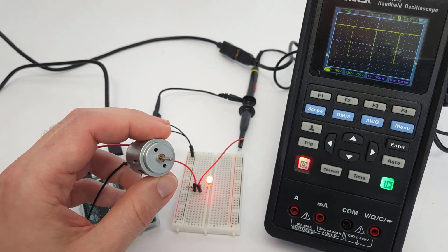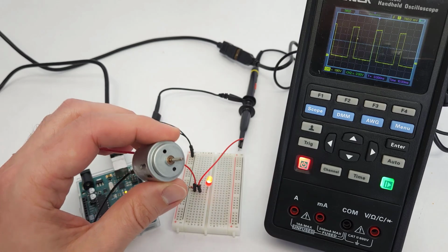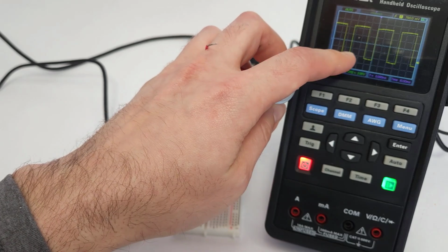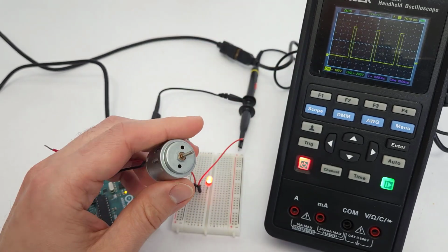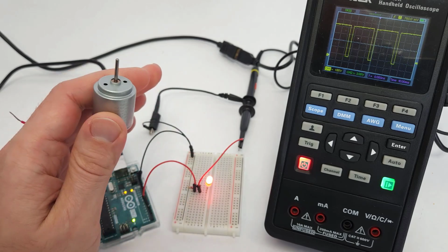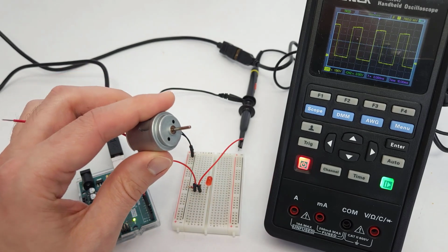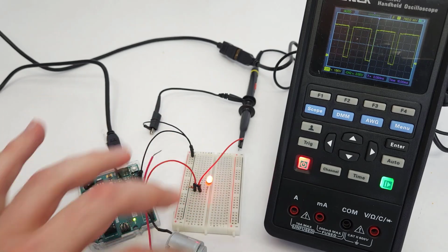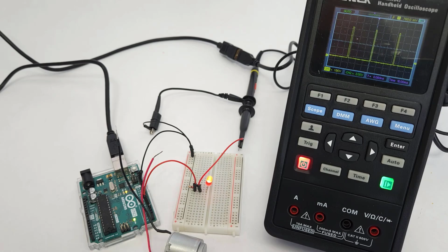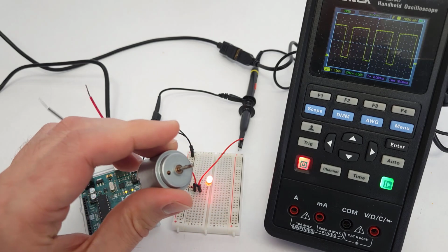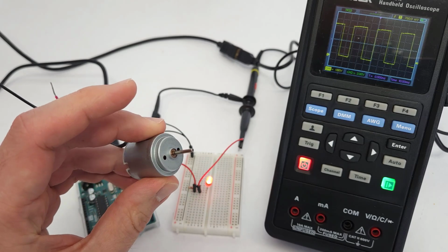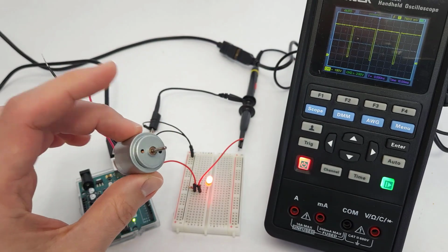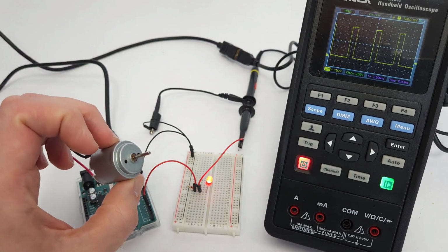Again, there's a whole lot going on there, but point being, you now have the tools to control the duty cycle and to very coarsely control the period by the factors of this prescaler, so 1, 8, and so on. Next, we are going to look at how you can even more precisely control the period if, for example, you wanted to do something like control a servo, which I don't have handy on my desk to grab at the moment, but we'll switch back to the computer and talk about how the servo control protocol requires a square wave at a specific frequency, so how you can use the timers to generate that.